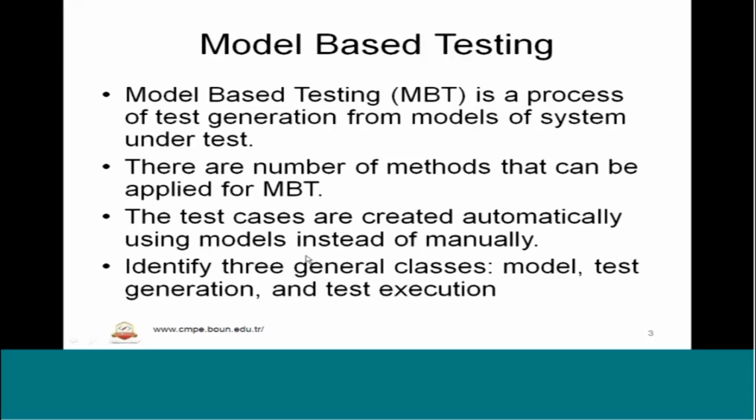Test cases are created automatically, as I said. The same test cases, with the help of test hooks, we will generate as scripts and execute on the target board. The target board already has the modeled code which is executing on the target. So basically, three classes are identified: model, test generation, and test execution. These are the classes they describe for MBT, model based testing.